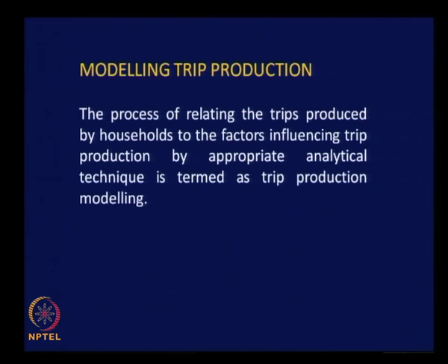Now, let us come to modeling trip production proper. The process of relating the trips produced by households to the factors influencing trip production by an appropriate analytical technique is termed as trip production modeling. It is very simple to understand. We are trying to relate the number of trips produced to a set of influencing factors, and this process is what we call trip production modeling.